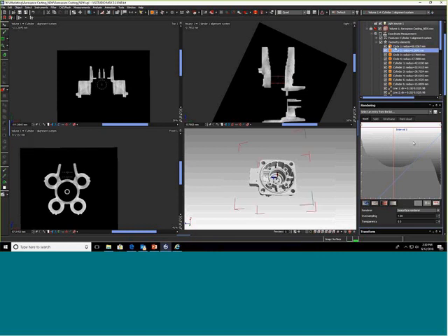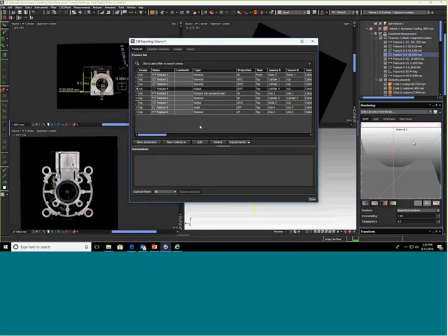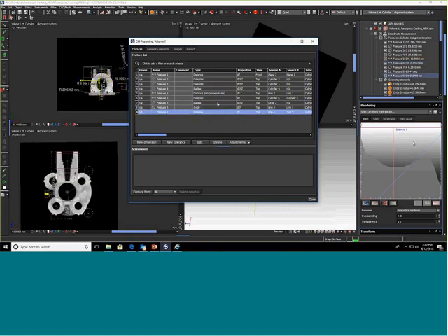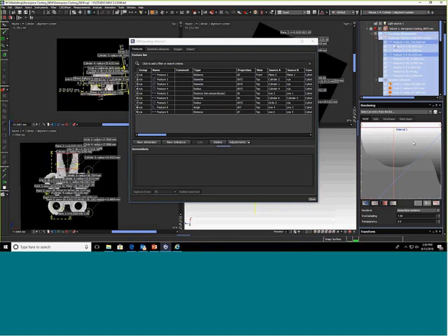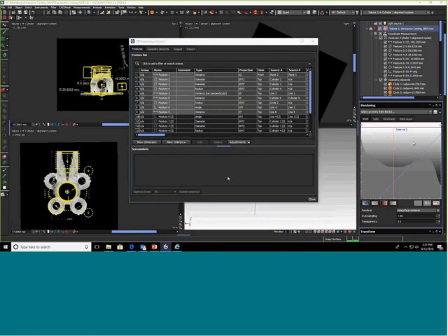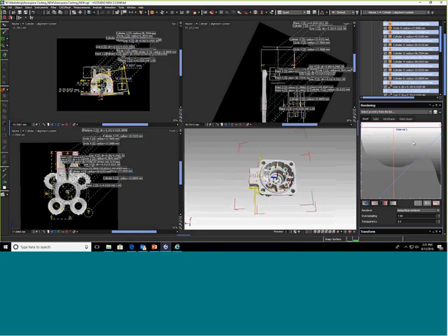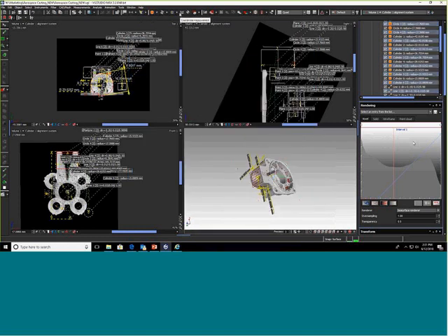So what we're able to do is you can actually see all the measurements and how they're taken and where they're taken at. Basically, we can create full measurement templates. And then if we wanted to apply that, let's apply that same template that was created on the next part. And it takes that long. It has the full gamut of GD&T controls as per ASME Y14.5.